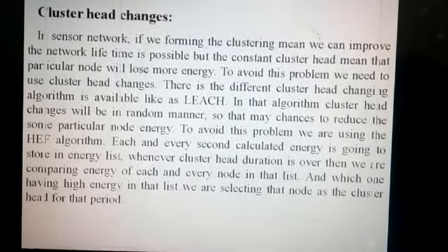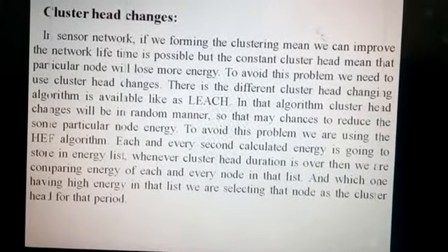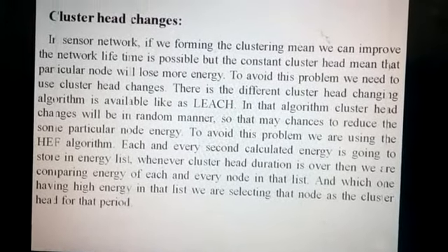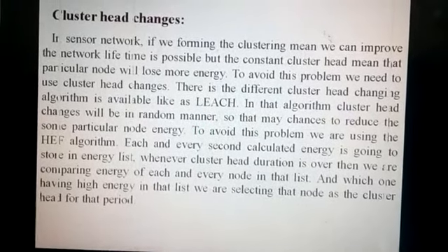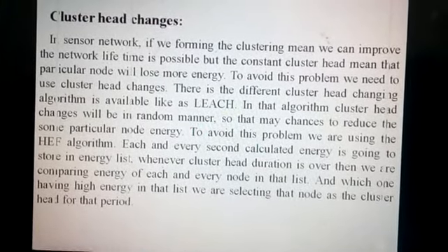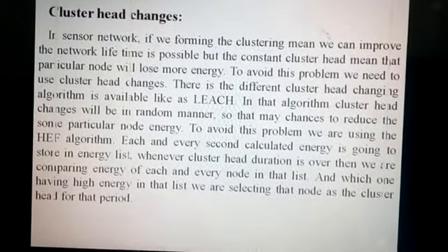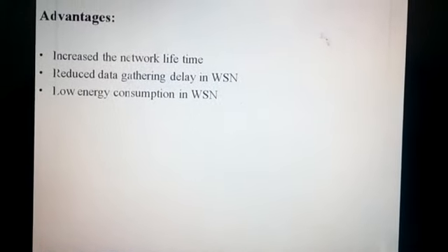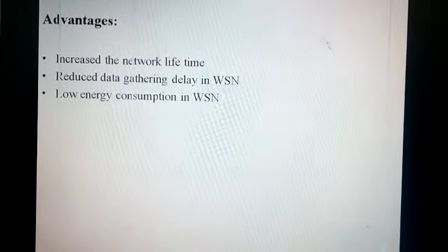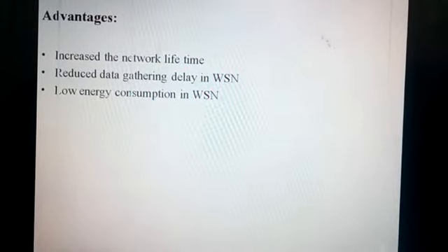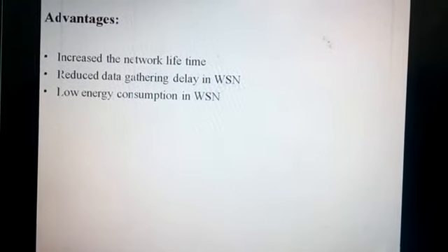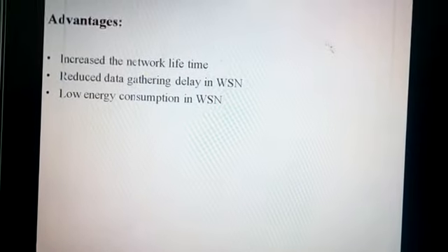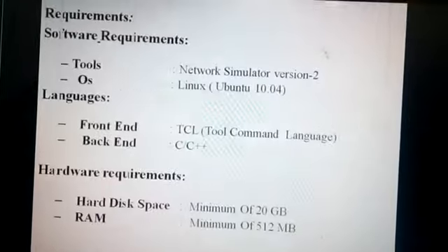Each and every second, the calculated energy is stored in an energy list. Whenever the cluster head duration is over, we compare the energy of each and every node in that list, and whichever has the highest energy in that list, we select that node as the cluster head for the period. This is the cluster head change. The advantages of the CHEF protocol in WSN are increased network lifetime, reduced data gathering delay in WSN by periodically changing the cluster head, and low energy consumption in WSN.